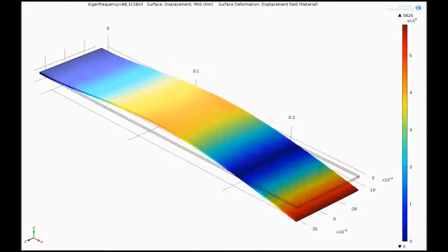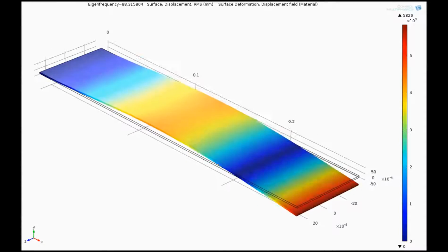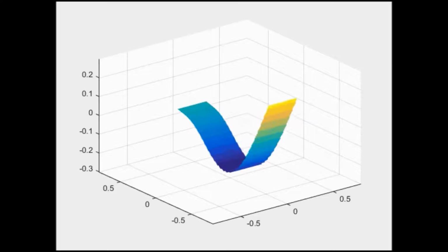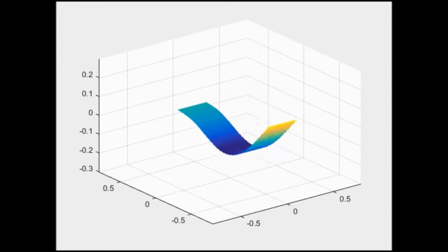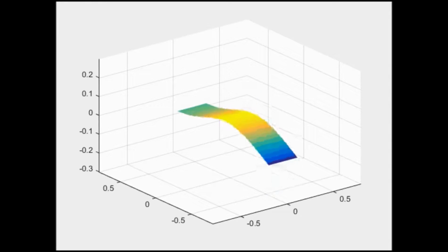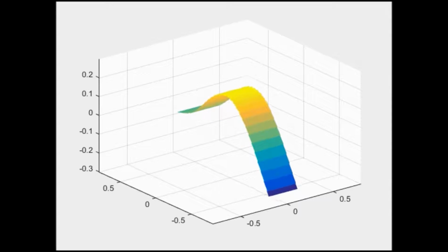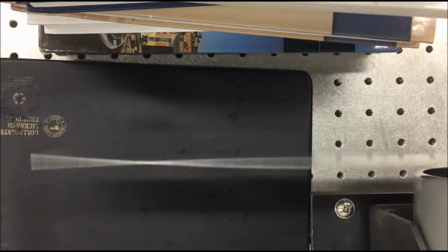At the second natural frequency, a second node becomes visible. The beam is now stationary at two different locations, and you can see the beam vibrating about these 2 points. Here is actual footage of the second mode shape. You can clearly see the node point.